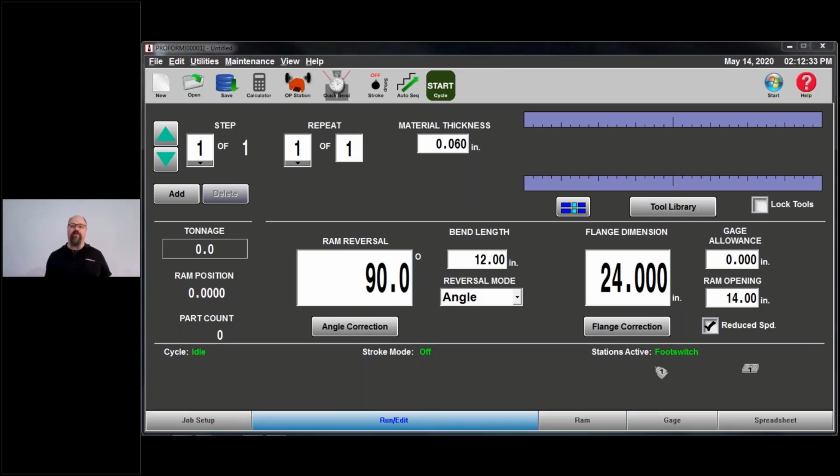A lot of my customers that are bending PVC or Lexan will actually heat their material up to get it to be more pliable, and they will thermally set the bend. They'll have the part sitting at that bend and let it cool while it's held in the tools. That way, when it cools down, you experience less spring back.